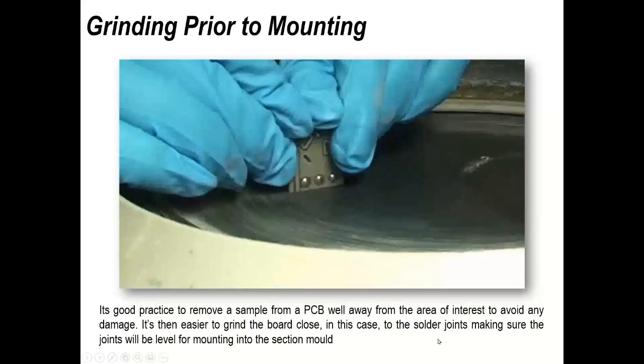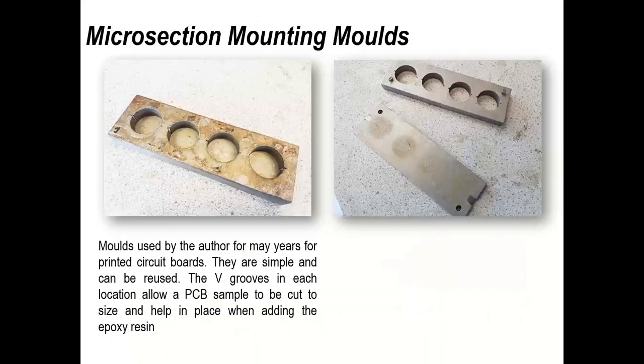So you can just see I'm using a grinding paper, we've got water lubricating the surface, and I'm just slowly grinding down till I'm closer to the area of interest.